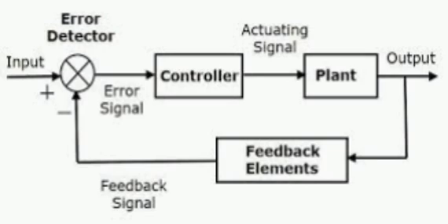Routh-Hurwitz criterion. Purpose: to find closed loop system stability, the number of closed loop poles on the right side or left side of the s-plane, the range of k for a conditionally stable system, and the value of k required for marginal stability, thereby determining the frequency of oscillations. To find closed loop system stability using the Routh criterion, we need the characteristic equation, that is 1 plus G of s H of s equals 0. Generally, the nth order characteristic equation is a0 s power n plus a1 s power n minus 1 plus a2 s power n minus 2 and so on, plus a n minus 1 s power 1 plus a n equals 0.